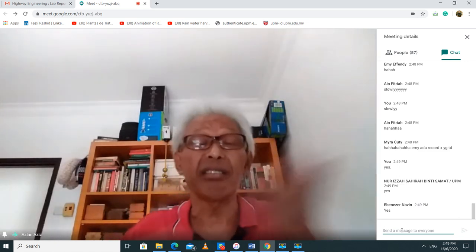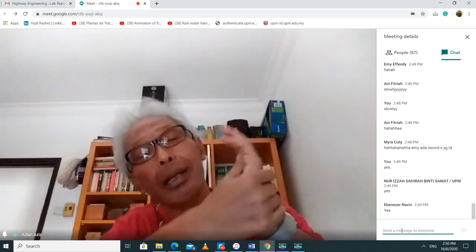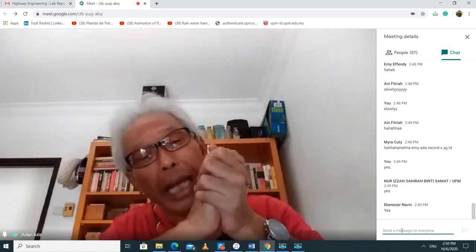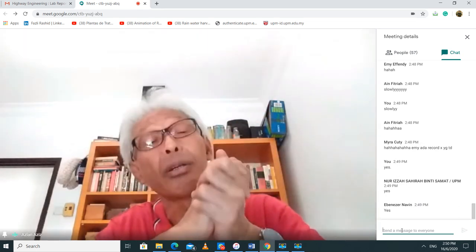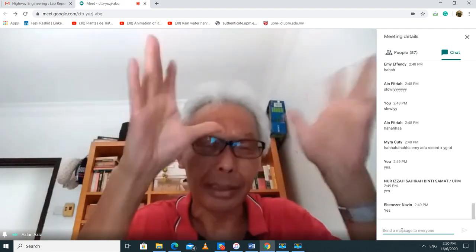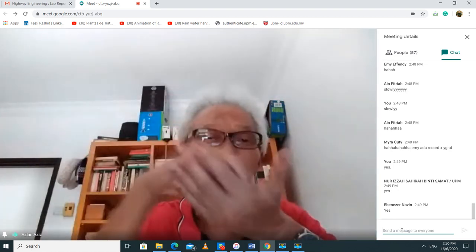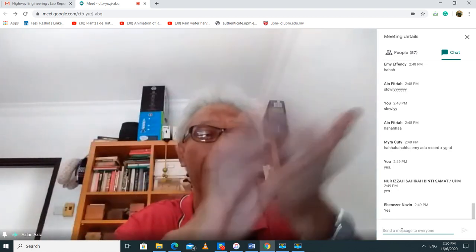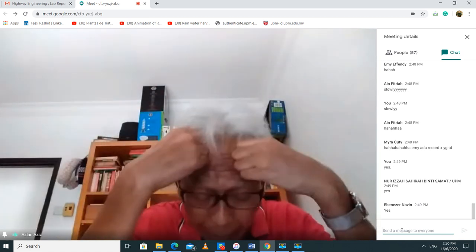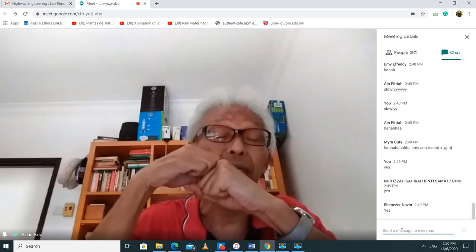Okay, C is that thing that gives you your cohesion. See, the gum, the glue, if you like, for a small particle. It's not a good way of learning things by saying glue, but I'll take the easy way to tell you that it's the glue. If you have clay, you put some water on it, you feel that the clay is sticky. Okay. Phi is for a grain.